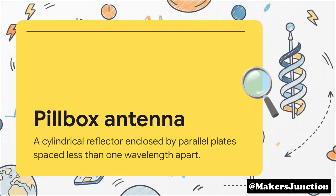Next is the pillbox antenna. Now, if you remember the cheese antenna we literally just talked about, the pillbox is almost identical. It's that same cylindrical reflector enclosed by parallel plates. But the key difference? It's all about distance. In a pillbox, those plates are spaced less than one wavelength apart.